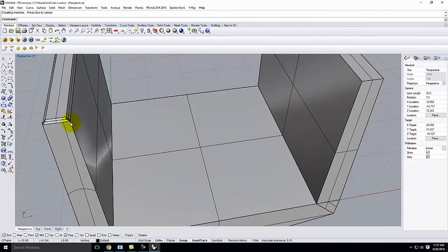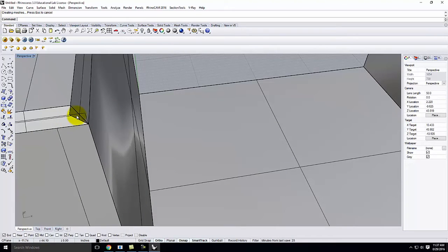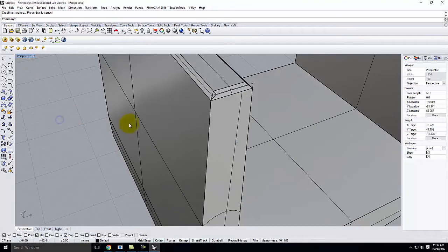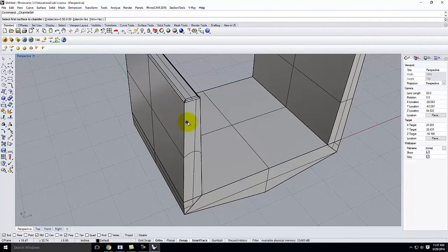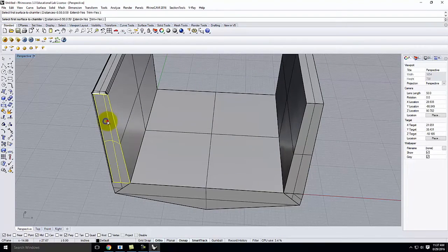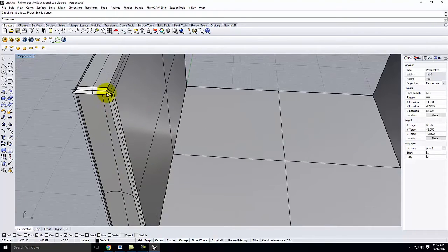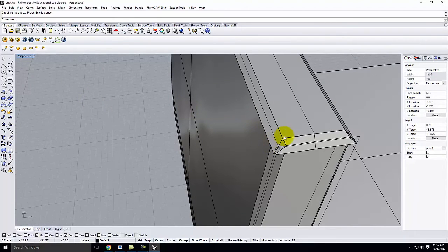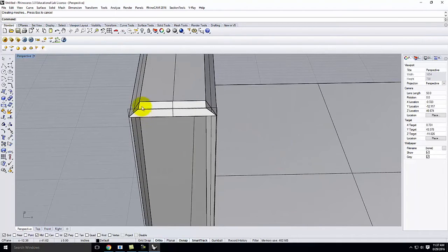That also looks good, but you can see that I'm starting to create these weird little pieces that are hanging on. So let me go ahead and chamfer this, and maybe this and this. Now if we start to look at these, you see that I've got chamfers on all sides, but I've got little pieces that haven't been trimmed. This is where I want to start to do some more work and really refine my edit.